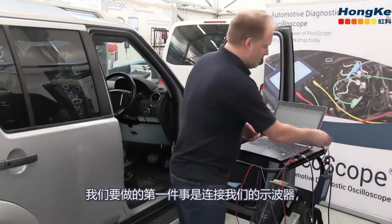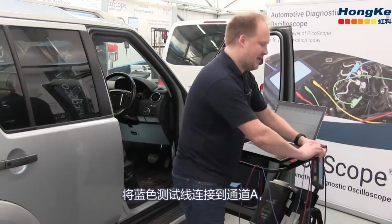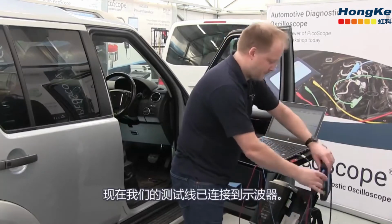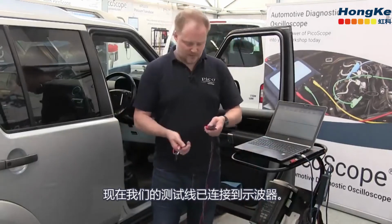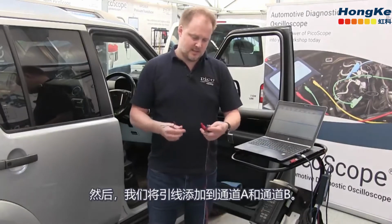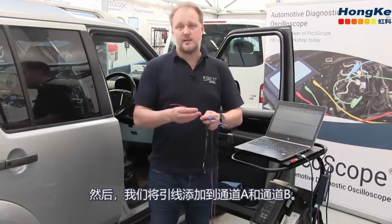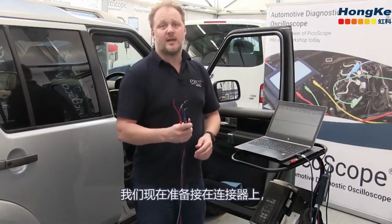So the first thing we're going to do is connect up our scope. We're going to connect our blue test lead to channel A and our red test lead to channel B. So now our test leads are connected to the scope. We're going to connect the two earth fly leads together and add a breakout lead. Then we'll add a breakout lead to channel A and to channel B. So we're now ready to pin out at the connector.